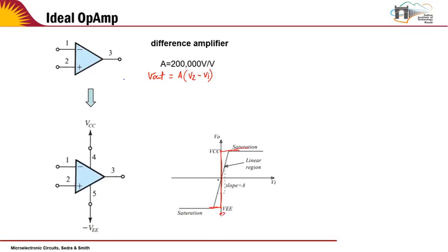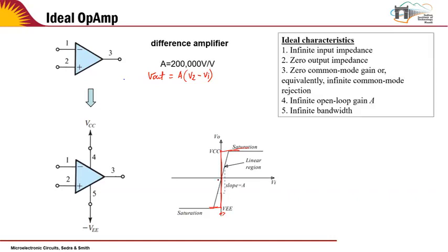The circuits that we analyzed last time use some rules, which we called the ideal characteristics. The ideal characteristics of the op-amp were that it has infinite input impedance and 0 output impedance. This is what we desire in any amplifier circuit. High input impedance, so that any signal voltage which is applied will fall at the input, and any output which is taken out from the amplifier will go entirely to the next stage without having any voltage drop over here.